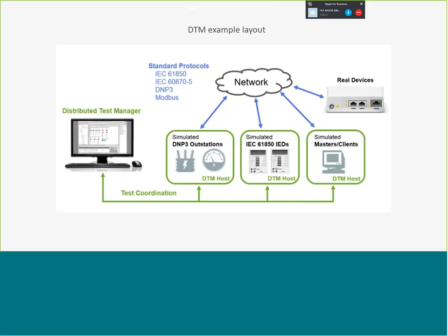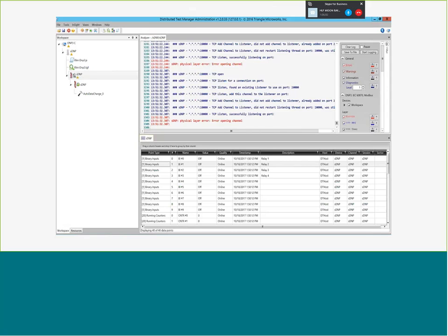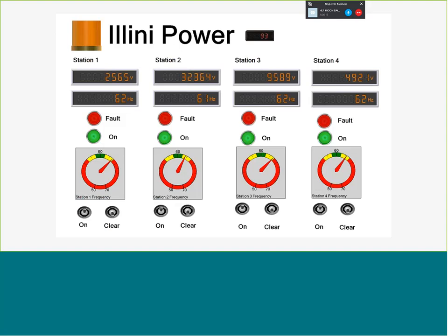So here are some of the capabilities. You're able to do Modbus, DNP3, 61850. You can talk to real devices, fake devices, more or less what we can do, but on the proprietary side. If you look at the software here, you have the point list for DNP3, you have your log manager and all your network topologies for DNP3 if you want to talk to real devices, fake devices, and what have you. It also has a really nice scriptable feature, so the events and all of that can be scripted using JavaScript. You can create fancy interfaces such as this, which we currently do not have in our software, but will be building out in the foreseeable future.